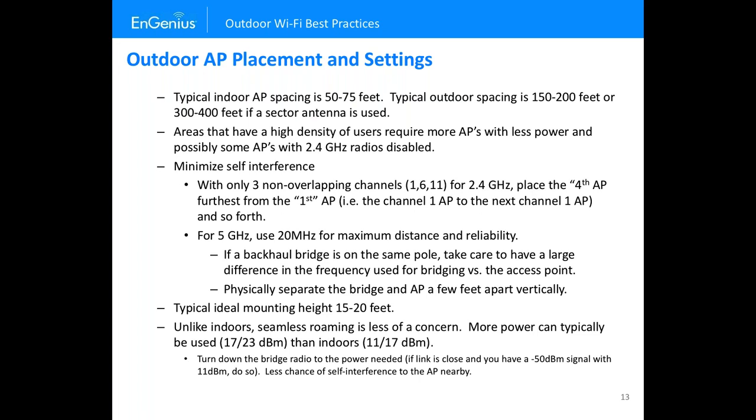Go with, like, we have a 19 dBi sector. That usually punches at least about twice as far or better in distance, but it is 120 degrees instead of 360. So a sector could be used to go much further without having to mount another pole. It could create certain areas of coverage, but it actually goes further in the direction it's pointed. So that could be useful, depending on the application, of course.